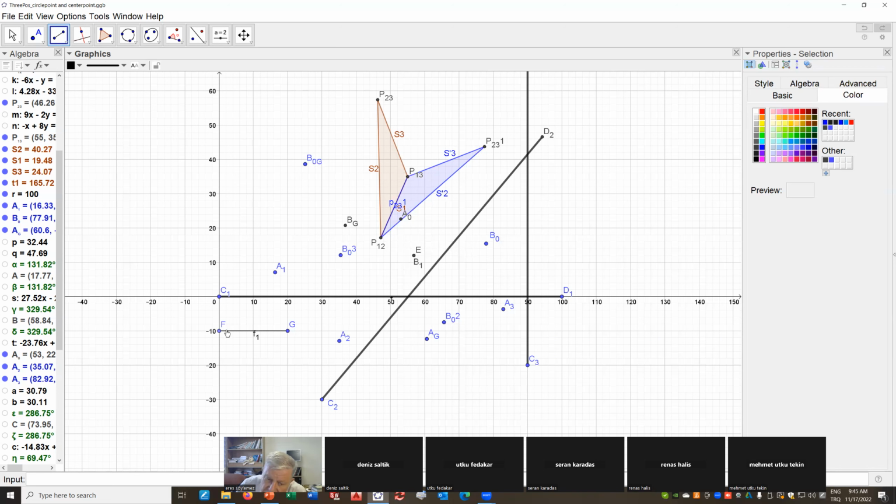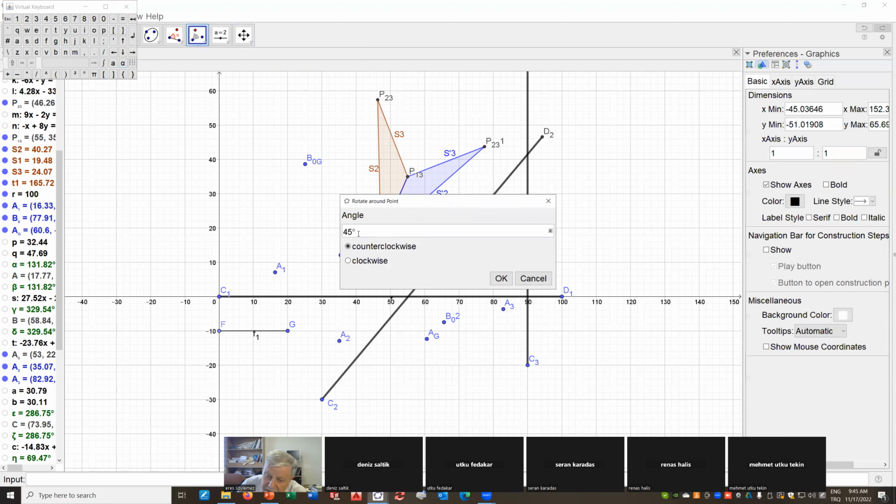Now, when I do it, since this is a fixed frame, if I'm going to keep the relative positions the same, FG is going to rotate about P12 by an angle minus phi12. Let us do that. Let me rotate this body. I know the angular rotation is 50 degrees, but this time minus 50 degrees. Okay?